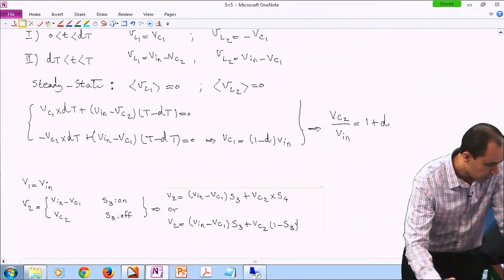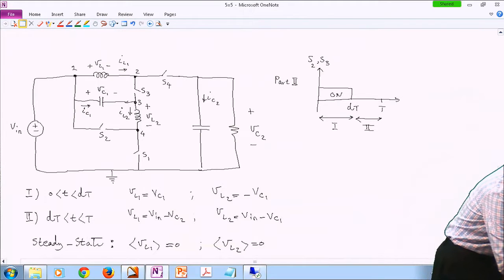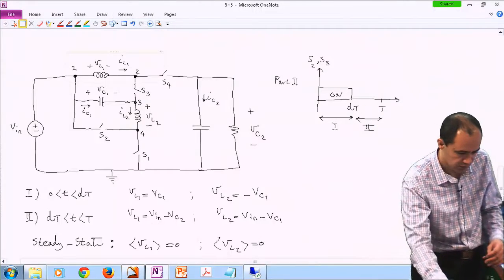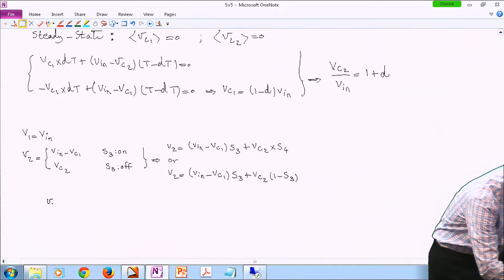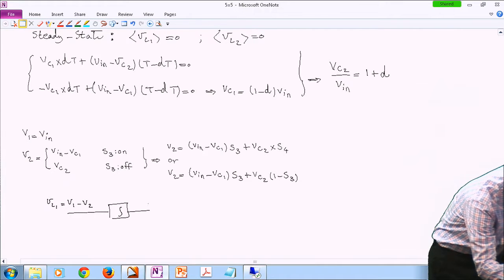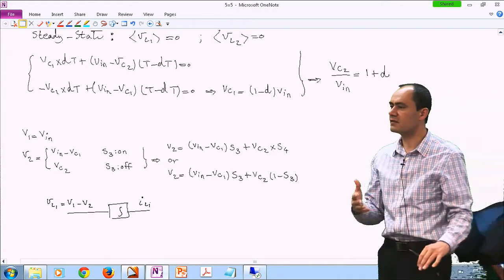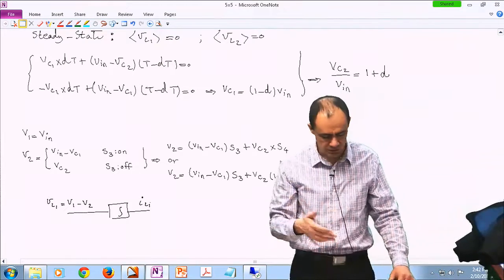All right. So I have V1, I have V2. So I successfully determined V1, I successfully determined V2, and V1 minus V2 is nothing but the inductor voltage. So technically, you can argue that VL1 is nothing but V1 minus V2, and then you use an integration block to give you IL1. Having the voltages available and having the switching functions available, you can actually construct all the currents of the inductors.